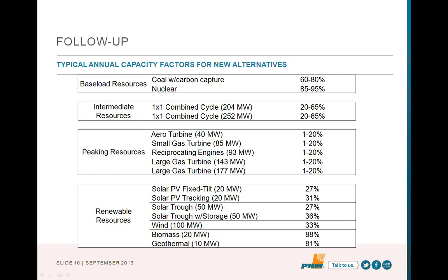So the way we address that in the modeling is we try to take something like capacity factor and vary it over a potential range and see if it affects our opinion on that resource. And for wind, the thing that tends to drive the bus isn't capacity factor, it's the contribution of capacity on peak. So yes, we look at that as a sensitivity in the modeling. The more important variable when we're looking at the wind farm is how much it is producing on our peak demand.